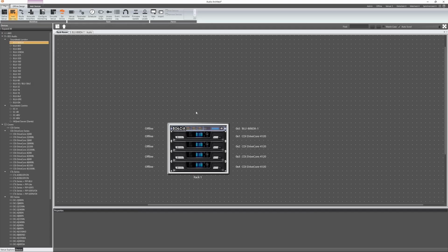So then this is our total rack for the whole venue, which density-wise is fantastic, because in a lot of other venues, you end up with probably double the amount of amplifiers trying to do the same amount of speakers. So it's really thinking about that compromise between cost, density, how many channels you need, how you want to set them up, especially linking them, whether you want to just daisy chain them, depending on your setup. Some situations like restaurants and stuff, you are going to basically just be daisy chaining smaller speakers to create zones.